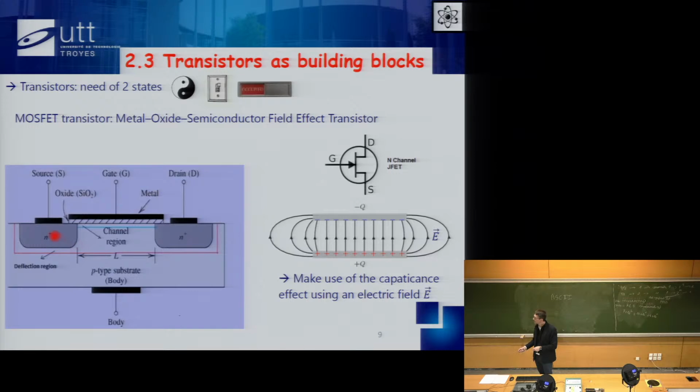Okay, so here's what it looks like. You have again these different doping, so these different materials with different doping, which have more or less electrons to more or less conduct in one side or the other. So here you've got n-doped elements, and you can see that in between them there's a p-doped material. And that's what stops the current flow going from this component to this component. So that would be the source, that would be the drain.